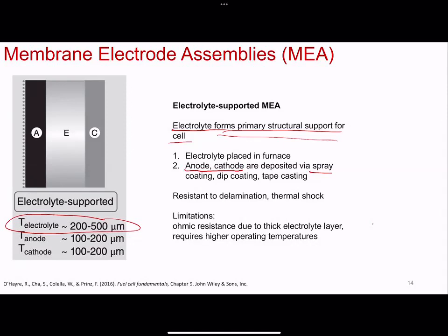The other potential issue, now it's not always an issue if you need to cover this area, but the areal size could be a limiting factor. Sputtering machines are not gigantic like this. But they could potentially achieve more uniform thickness, so that is an advantage. But with most sputterers, you have to evacuate the system. It can't be done in an ambient atmosphere.